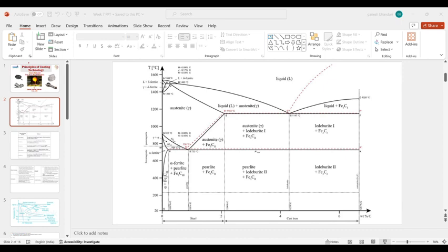If you go with normal heat treatment after the surface heat treatment, the sample will get that temperature and your carbon will diffuse more, deeper into the sample, up to more depth. So your properties are going to change up to some level. So first you have to go with normal heat treatment process, then you can go with surface heat treatment processes.